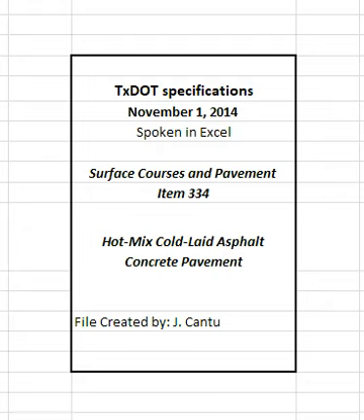Provide aggregate stockpiles that meet the definitions in this section for coarse, intermediate, or fine aggregate. Supply aggregates that meet the definitions in Tex 100E for crushed gravel or crushed stone. The engineer will designate the plant or the quarry as the sampling location. Provide samples from materials produced for the project. The engineer will establish the surface aggregate classification, SAC, and perform Los Angeles abrasion, magnesium sulfate soundness, and micro-Deval tests. Perform all other aggregate quality tests listed in Table 1.